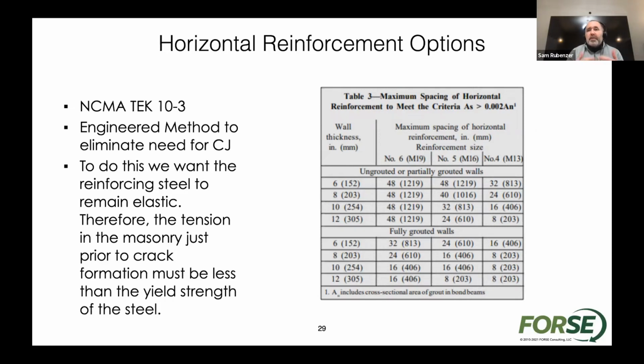If I'm relieving them every 25 feet, I need a lot less reinforcement. If I want to completely restrain those stresses from developing and opening up cracks that are too large, there is an amount of reinforcement I can add. It's about 3 times the amount of reinforcement I would add if I wanted to keep control joints. So hopefully that makes sense.